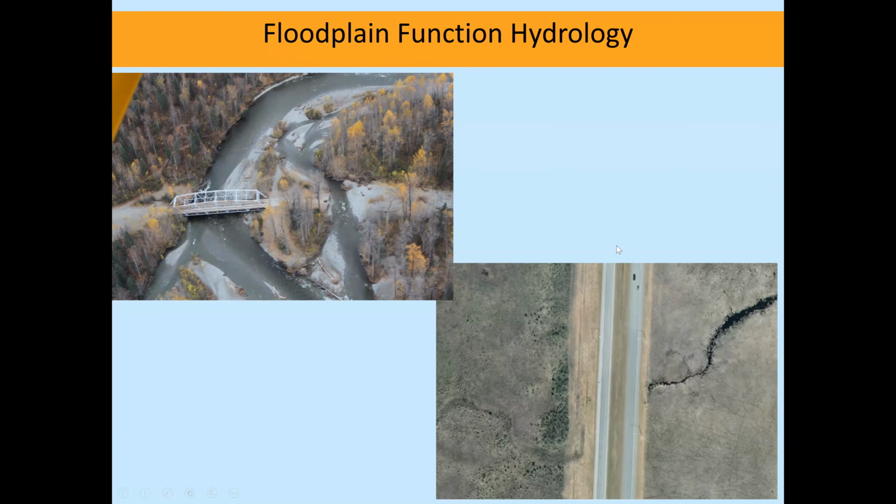And I think that might be a good thing to think about: the crossings that you're designing could have subtle changes, maybe a little bit of temperature change here, some vegetation change over time, maybe some sediment building up in different ways upstream and downstream. But overall, over time, it's changing the stream and floodplain function from its natural condition, from what those fish and aquatic life were adapted to, to a new one that may not be as ideal for them.